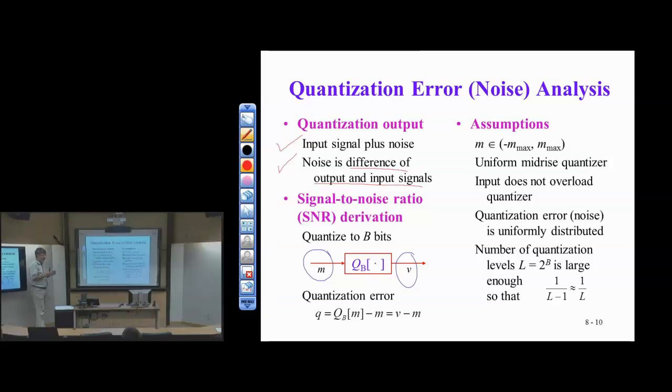Okay, so that is, and in practice uncorrelated. Well, not so much in practice. But again, it's an approximation, an assumption we're going to use to get to this formula. There's another approximation coming, so these are good to keep in mind as the limitations of this approach. All right, so we're going to quantize to B bits. And this is true in general.